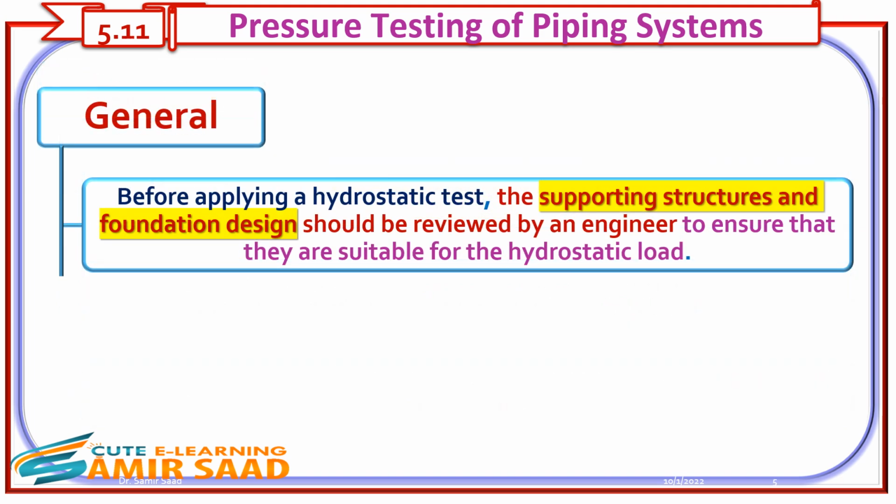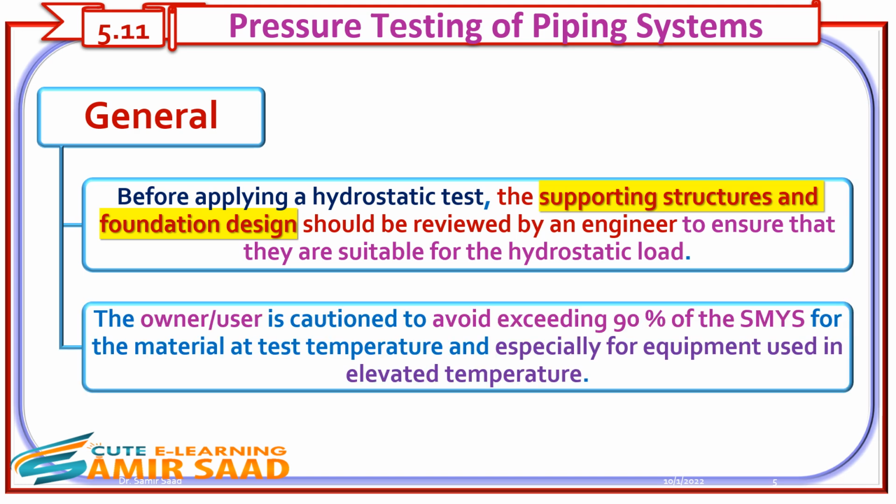Before applying a hydrostatic test, the supporting structures and foundation design should be reviewed by an engineer to ensure that they are suitable for the hydrostatic load. The owner-user is cautioned to avoid exceeding 90% of the specified minimum yield strength for the material at test temperature, and especially for equipment used in elevated temperature.